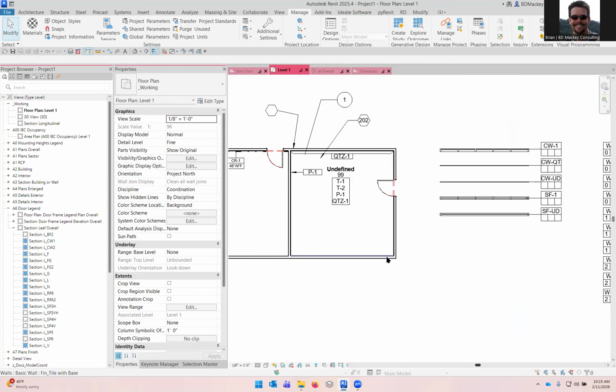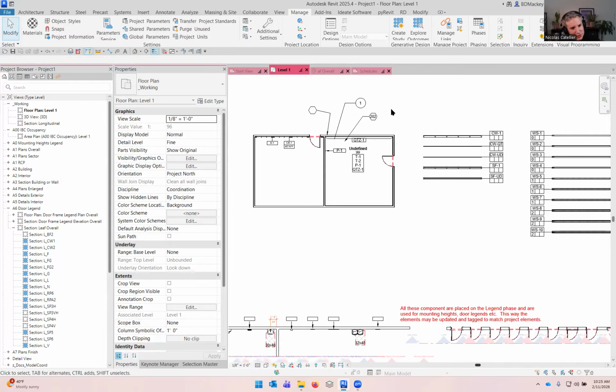So yeah, but in your case, like in an elevation or whatever else, if I've modeled the object, I absolutely do a material tag. It's either a material keynote tag, if that's how you work, or a material tag that's pointing to the material mark or name or something. Yeah. So what about exterior elevations? How would you annotate these? I still do, like you said, a material tag, because as I'm modeling those exterior elevations, I'm getting the material set up inside of there. So absolutely. Even if I'm talking curtain wall panels, I still tag the glazing, right? My material's got that value inside of there.